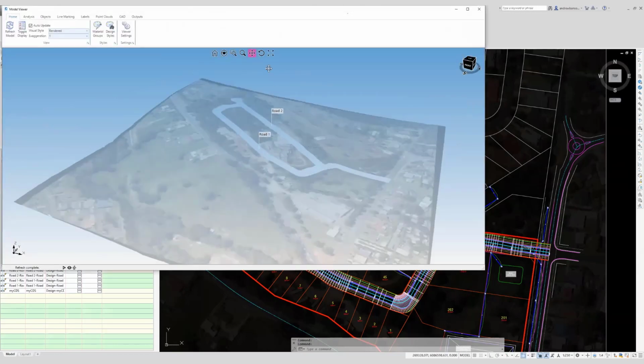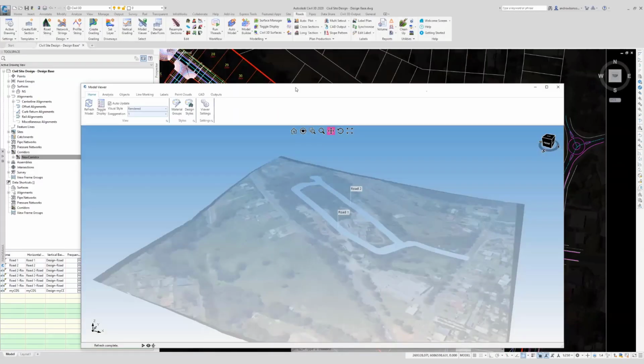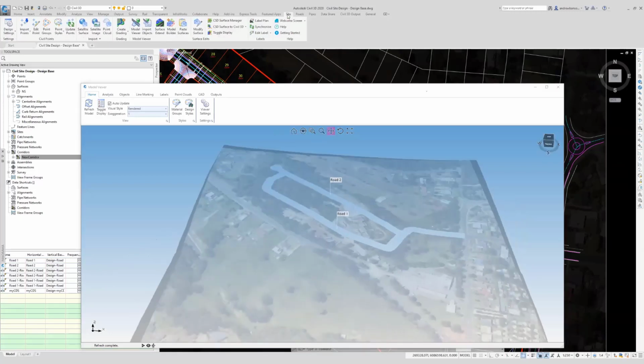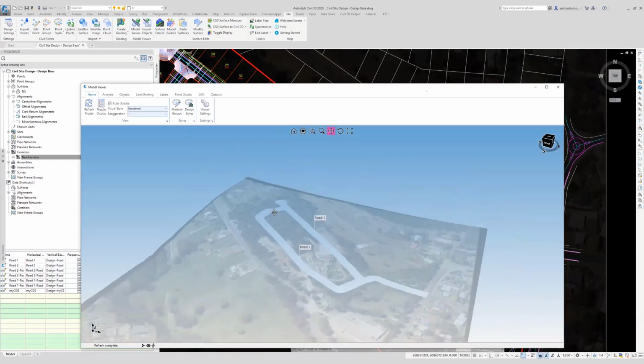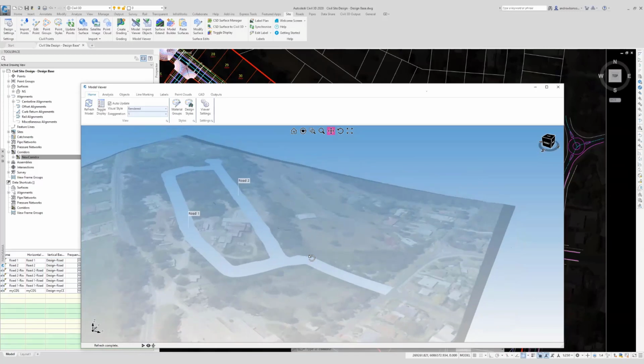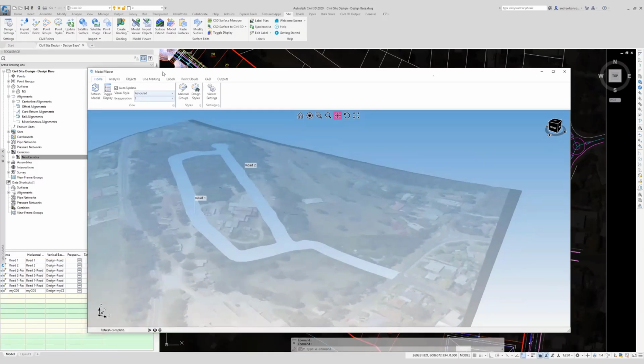What we did in the current version 20.3, there's actually a whole bunch of new features we haven't had time to sort of promote yet. But one of those is the ability to now import IFC files. Now, what I've done here is I've created a base surface using the paste surface command, and I just created a hole where my total model is. So you can import an IFC file now.